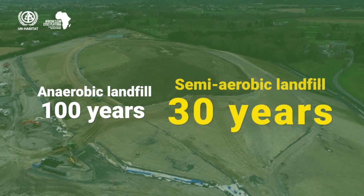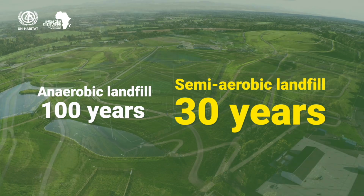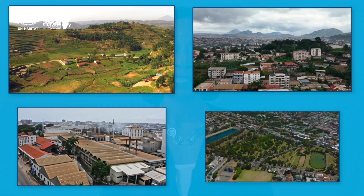Semi-aerobic controlled landfills offer a significant advantage in site stabilization, achieving stability in approximately 30 years after final usage and closure. This is a much shorter period compared to anaerobic landfill management. Once proper monitoring is conducted and site safety is confirmed, the stabilized landfill can be repurposed for various uses.